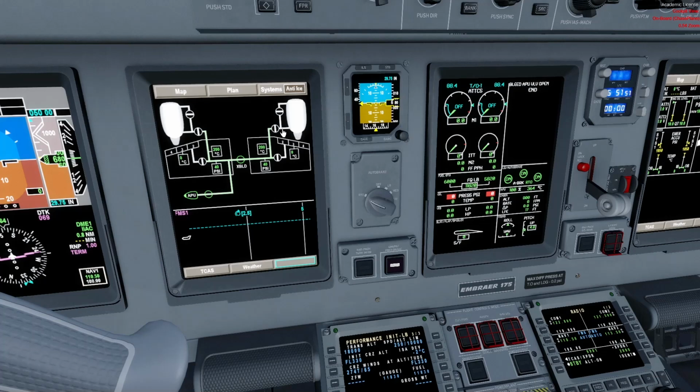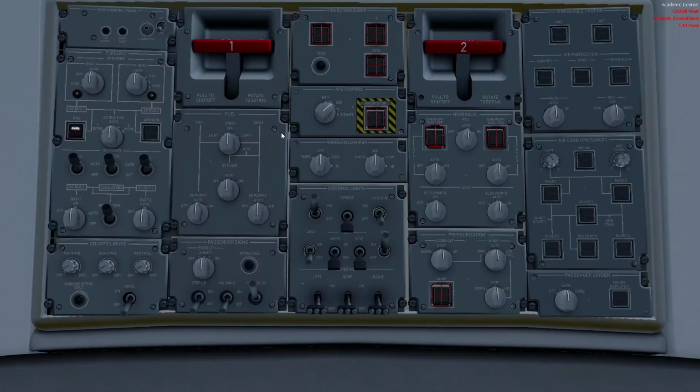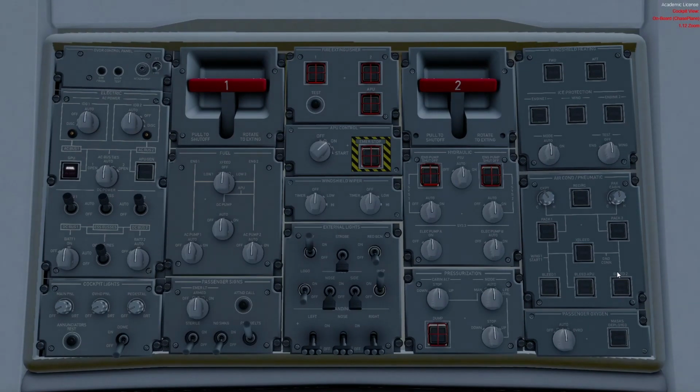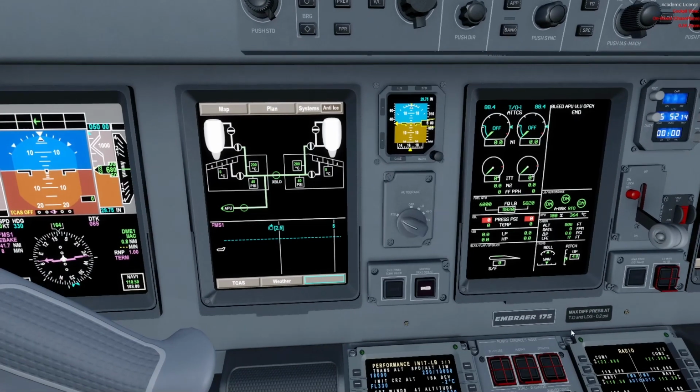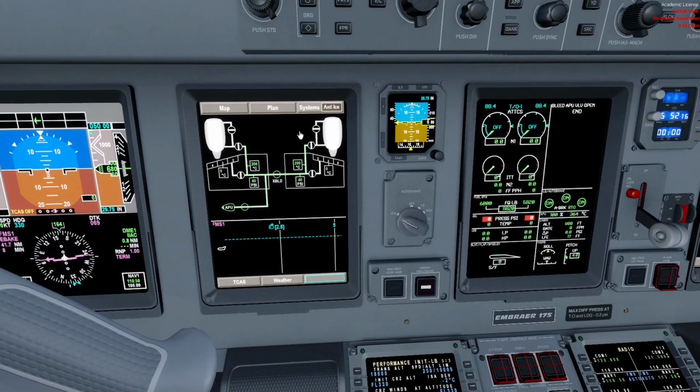You can notice that the bleed is taken from before it. The bleed valve I'm talking about for engine 2, this is the bleed valve. Right now it's pushed in, so it's the normal position, so it's enabled. I could push it out and it would be disabled. But nevertheless, that entire thing I just mentioned happens before that valve. Therefore engine anti-ice operation is not affected by whether or not this valve is being forced to close, or is malfunctioning, or there's an MEL or something like that.